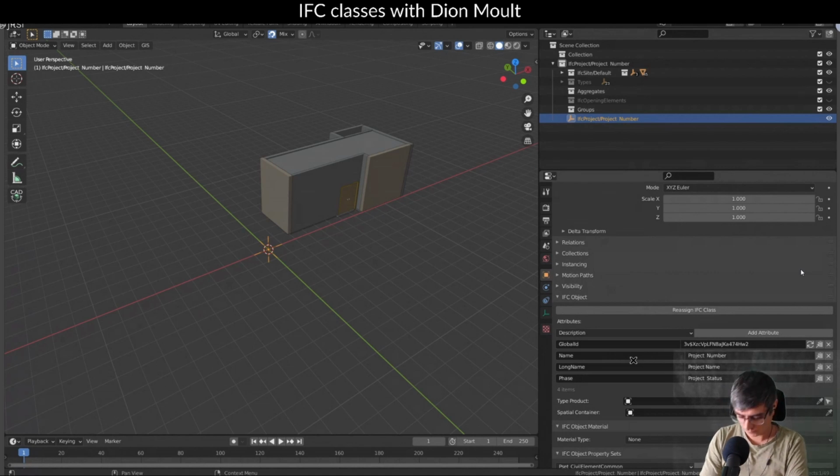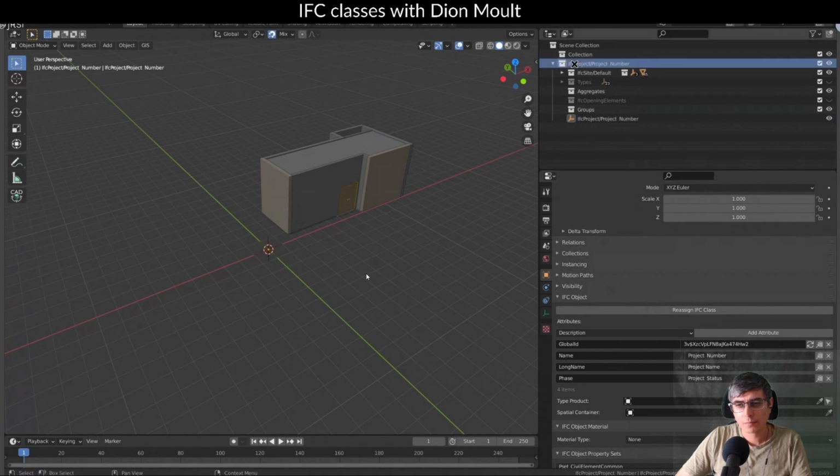But the reason why we want to talk about it is because the project class is the first class that people go to when they want to learn more about a piece of BIM data. When you give a BIM model to somebody else, you can give it to them in the form of a file or something else entirely, but there's a whole bunch of data in there: walls, buildings, sites and all that. But the first piece of information they look for, or any software looks for when it tries to understand your BIM data, is an IFC project class.